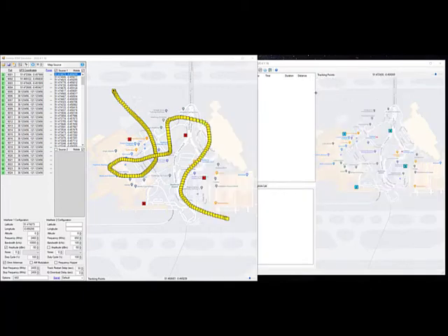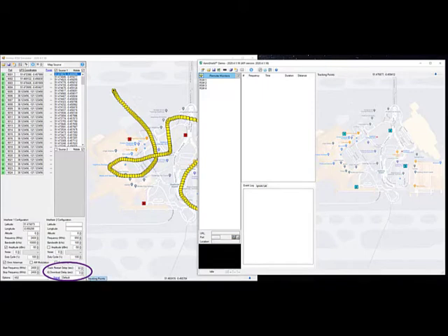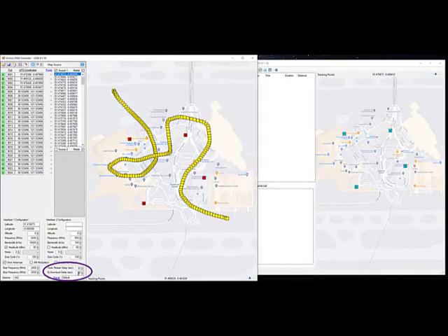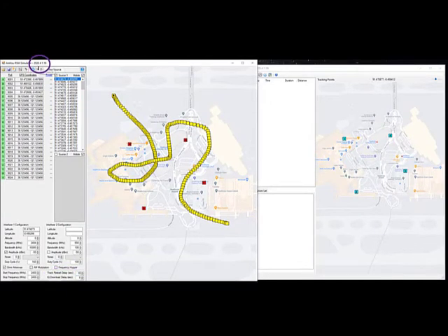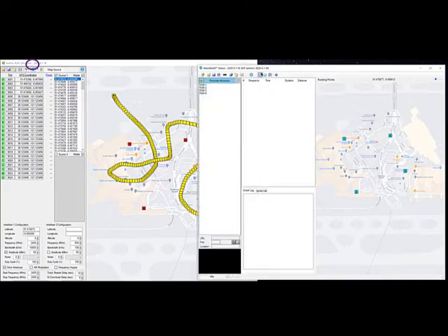Other settings to note in the simulator are the track reset delay, basically how long you wait until it resets and goes to another loop of a signal, and then the IQ download delay. Typically if you have fiber or a very fast backbone network, that's going to be 0. And then number of tracks per second we'll set at 1. So each iteration will be 1 second, and then hit start, and then hit start in our demo program.